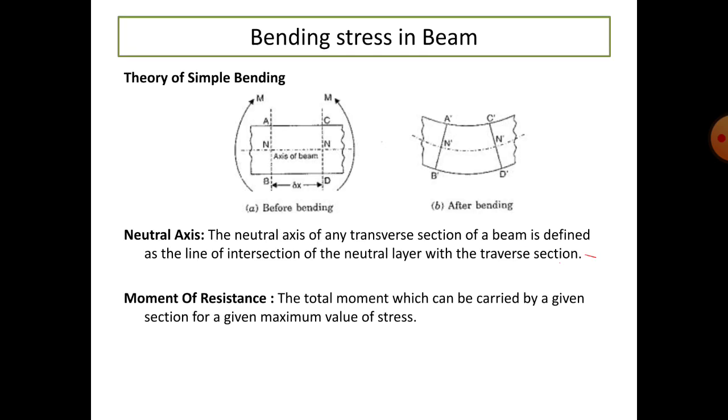Okay, and next is moment of resistance: the total moment which can be carried by a section of a given beam for a maximum value of stresses. When you apply a stress, the extent up to which the beam can resist that, up to the maximum, is called the moment of resistance. How much resistance the beam can provide to the given loading, that is called moment of resistance.